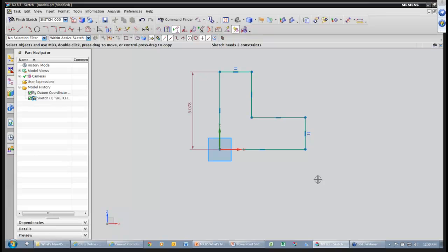However, as I mentioned, if you're used to the more object action, meaning I pick the geometry, then pick the constraint, if I grab a line and another line, you'll see that it pops up that floating toolbar, and as we discussed the organization, but notice how it pops up those available constraints here without even going into the constraints dialog. So if I just grab equal length, I've done that. So that's very, very quick just by grabbing geometry and accessing the constraint on the floating toolbar.